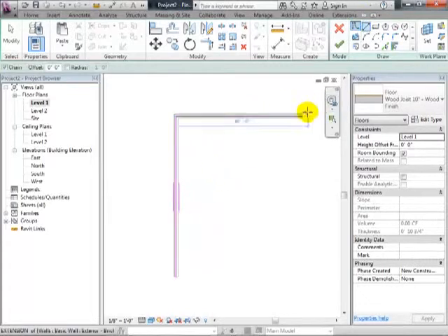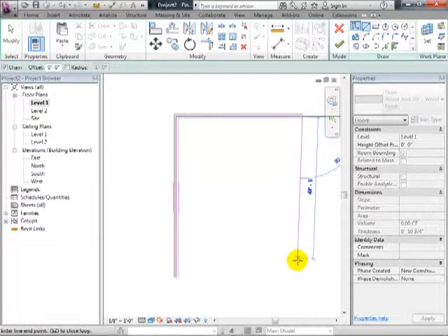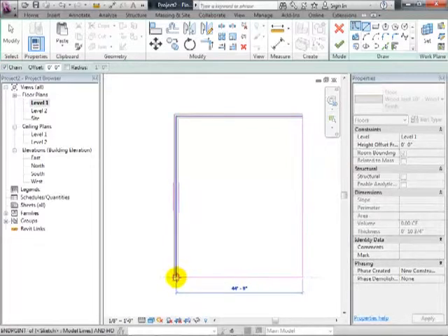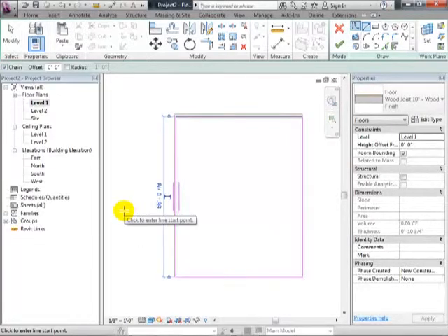To finish the floor, I'll just close it with some lines. Every floor basically has to have a closed continuous boundary. So if you're creating a floor and it's complaining at you, it won't finish the floor. It usually means your pink lines just aren't closing up and intersecting. So go ahead and get the one wall, get the upper wall, and then we'll close the other two. You got that one? That's beautiful.